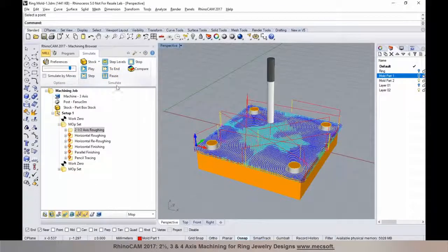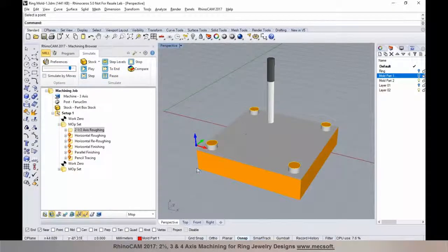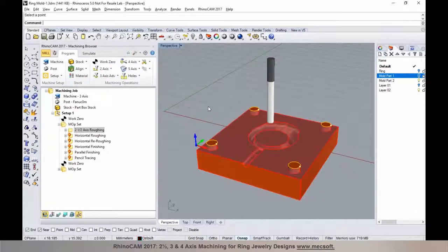So this is very similar to roughing in 3-axis. However, here, you're using a roughing for 2-axis operation ideal for prismatic parts. And as Joe pointed out, this automatically takes into account the extents of the stock that you defined. In this particular case, it just happens to be a rectangular stock, but if you're using a stock with any other shape, cylindrical or any odd shape, it'll automatically take that into account.